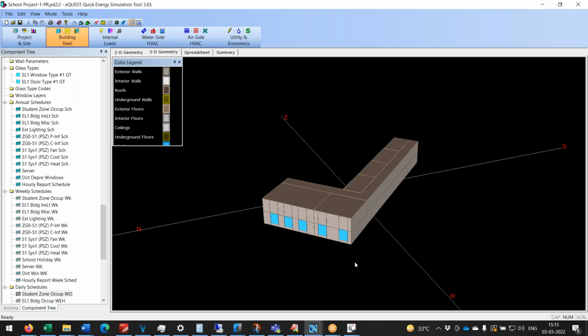Whereas in chilled water based systems, the AHUs have their own outlets for fresh air. So in those cases, TFA is not required. But if you want to provide TFA, you can still provide it. But for VRF and split, it's definitely required.